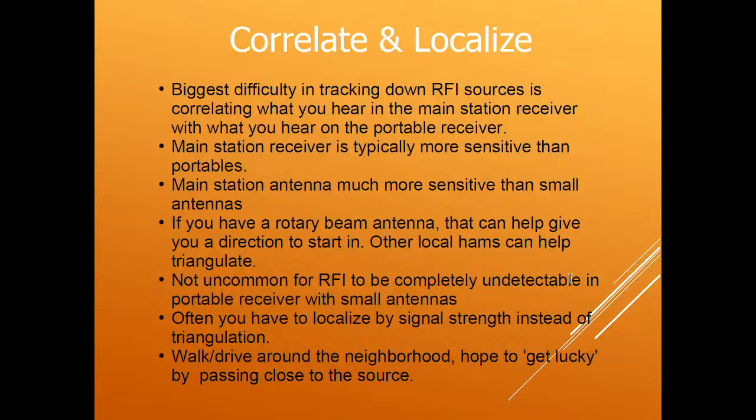If you have a rotary beam antenna, that's a good place to start. You can swing that through 360 degrees and figure out where the noise is coming from. Most antennas have a main peak response in the direction they're pointed, and that's fairly broad, so that may not give you a really accurate indication of the direction that the noise is coming from.